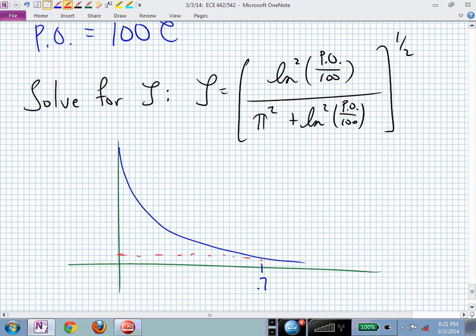So you have an equal real part and equal imaginary part. That gives you a percent overshoot of 5%, 0.7 for zeta. So this is our zeta axis. 0.6, and I'm not going to be able to sketch this very well, is about 10%. And this really gets pretty bad pretty fast. At 0.2, it's a 50%.